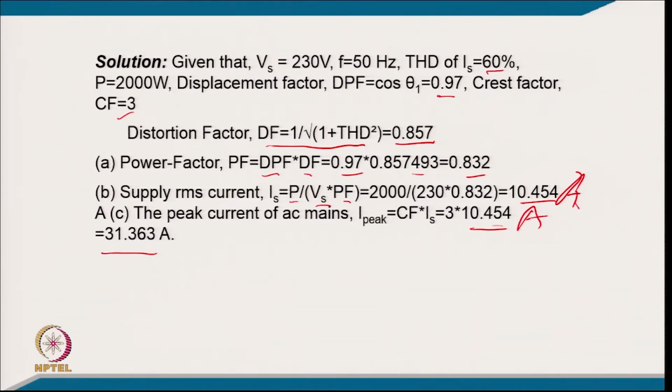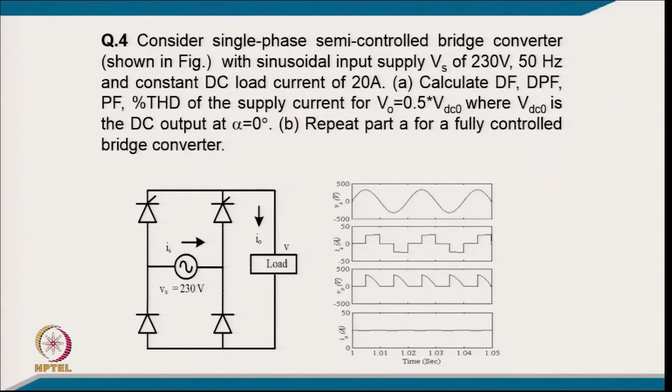There are many such loads in practice which have a diode rectifier followed by a capacitor filter, and this THD and crest factor depend on the relative value of the capacitor and the load time constant, that is, typically the equivalent load resistance.